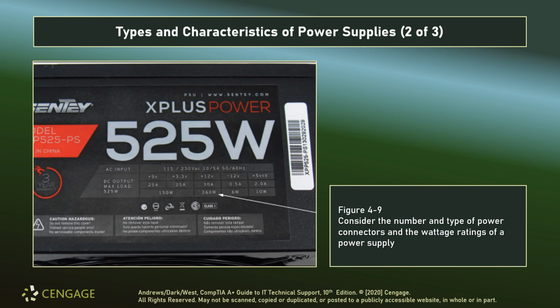That's the AC input. The DC output, what we would expect to see, maximum load of 525 watts. So we can see the big 525 in the model number, we can see the big 525 on the sticker, and we can see that it's also declared under the words maximum load. The 5-volt rail, standard 5, runs at 25 amps. The 3.3 also runs at 25 amps, and the two of them together, that's why they're kind of boxed in that group, is a maximum of 150 watts of power altogether.